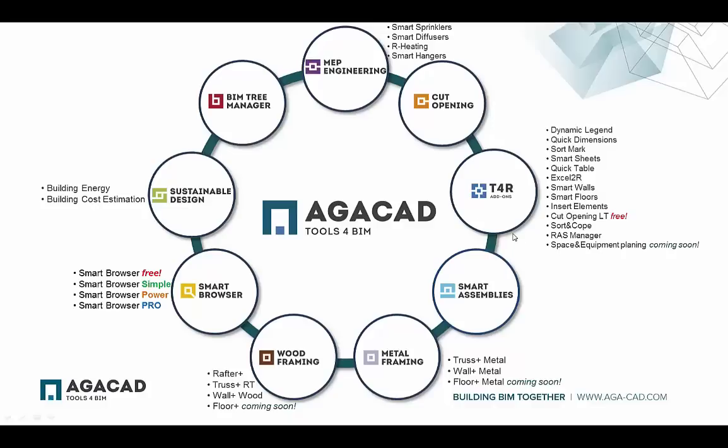Then tools for Revit add-ons. Here you can find different solutions for documentation and for modeling. So it's kind of small solutions, but at the same time very handy, for example, for adding dimensions or numbering elements and so on. Then we have Smart Assemblies. It's a very powerful solution for making assemblies automatically and for preparing shop drawings. So you can very easily select a precast wall, for example, and make an assembly with the dimensions, with the needed schedules, and place those views automatically into the sheets.